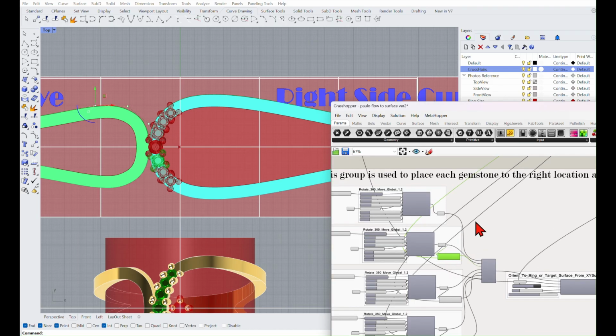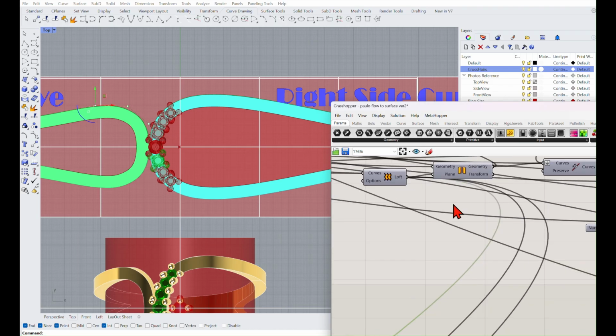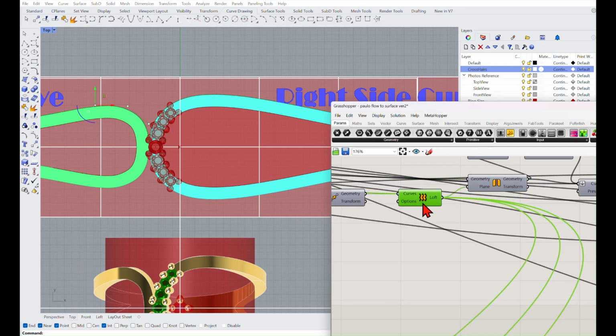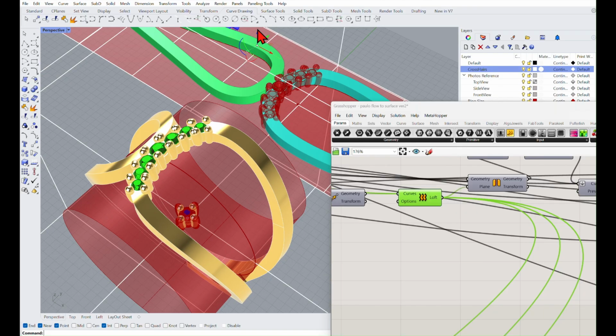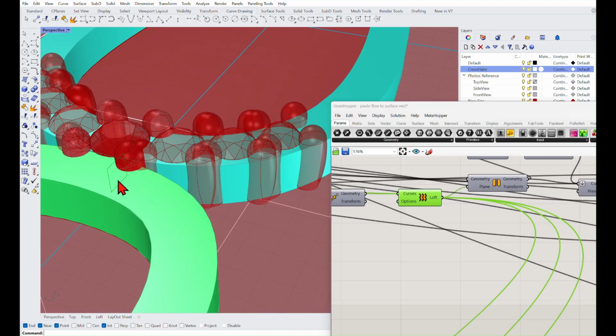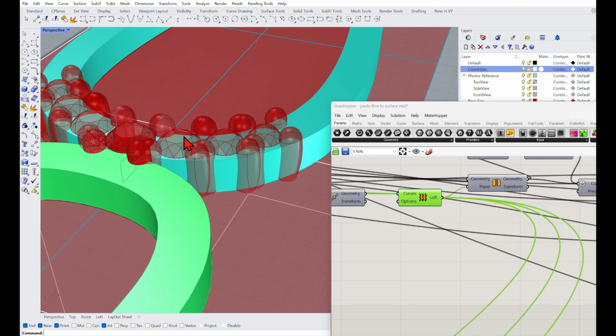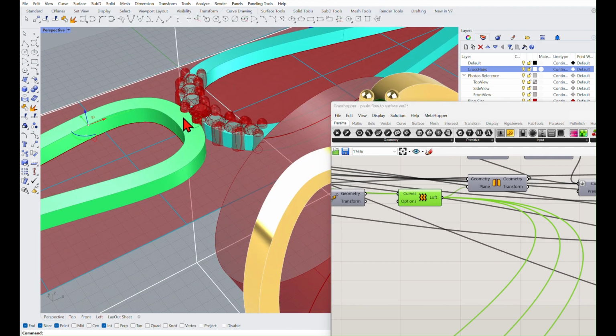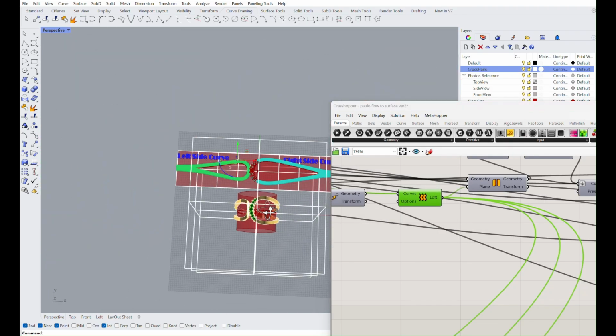Okay, the mirror is from a small surface that we've created in here. Right here, you can see it. And we're just creating that surface. It's not being used for anything other than a plane, so that everything we can mirror off that plane. So as we change the size and location of this particular plane, the mirror goes with it. Okay, so sometimes you have to think outside the box.